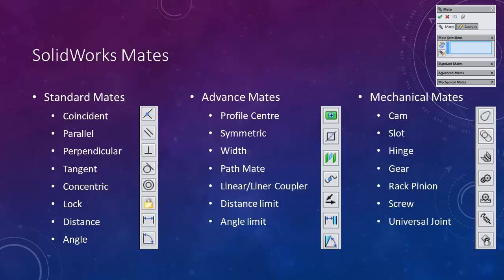There's a bit of a gap, but the width mate allows it to run within that slot and be central to it, or offset to. You can set a little factor to it, or you can get it to play within that slot and have a bit of degree of freedom, but only within that slot boundary there.